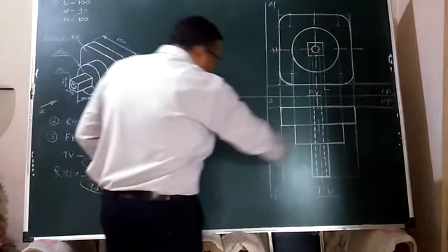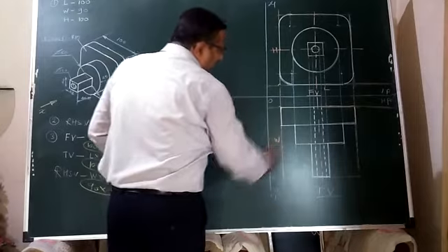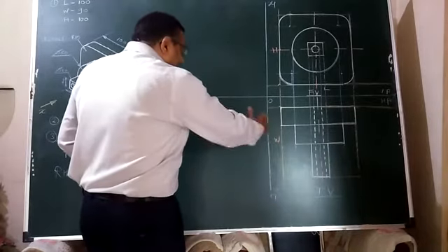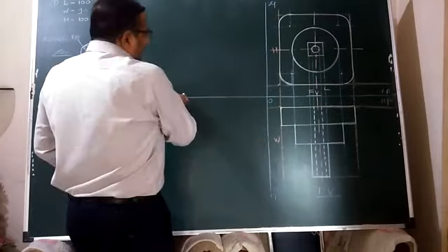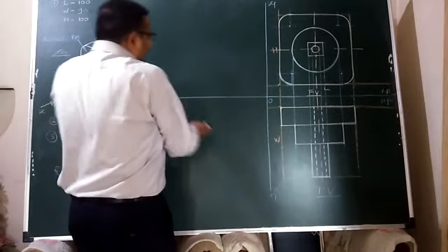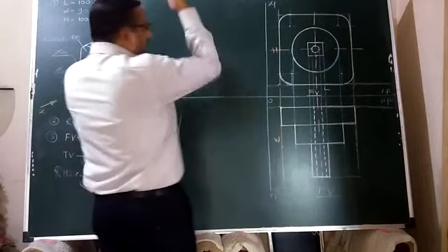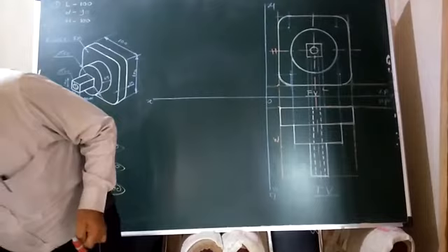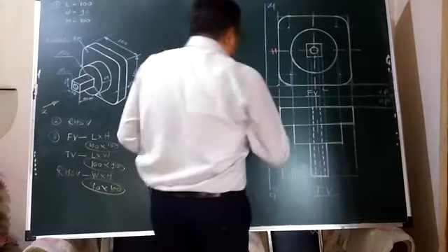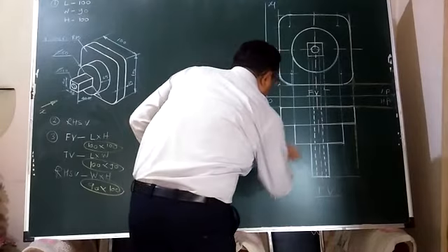Similarly, cross projection lines you will get while projecting these horizontally constructed or extended projection lines up to RL. From that, by compass only about O, you have to tilt through 90 degrees, and those will be tilted through 90 degrees from VRL to HRL. After that, again vertically up we have to run, we have to make them extend. So I will start projecting all these steps horizontally.